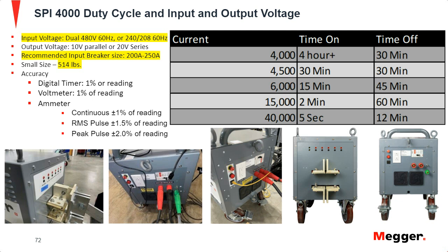It asks, would you conduct primary injection testing before energizing a brand new MCC low voltage breaker? And then they also ask, what is the minimum circuit breaker size that requires primary injection testing? So on the MCC panels, there could be breaker sizing ranging from very low amperage, like around 100, 125 amps, to very high, around 2500 amperes. It all depends on the type of motor and the type of load.